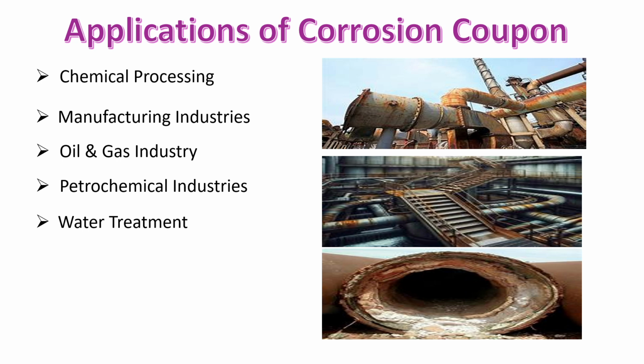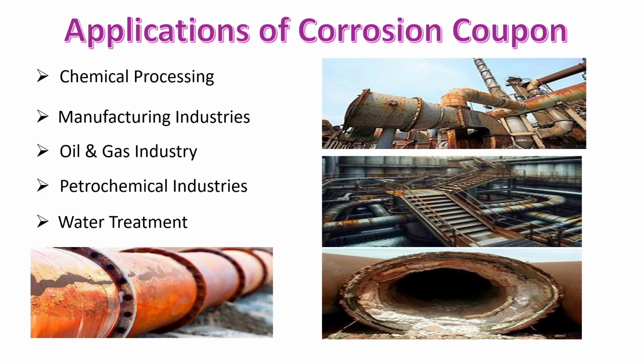This is the piping which got corroded due to incompatible material or the corrosive atmosphere, and scale formation is inside this. The complete piping material got damaged, and this is the impact of the corrosive vapors or atmosphere on the metallic surface. So to avoid this impact or breakdown, we have to select the proper material of construction for any of the equipment, that may be a tank, reactor, pumps, or anything. So that's why it is an important topic, and I have highlighted it here.